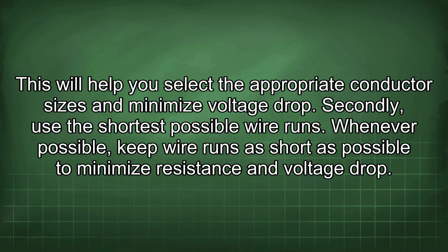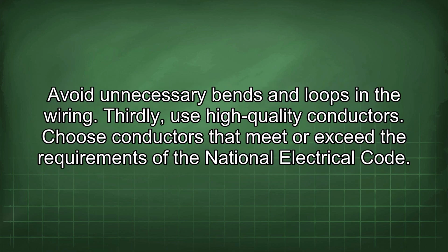Secondly, use the shortest possible wire runs. Wherever possible, keep wire runs as short as possible to minimize resistance and voltage drop. Avoid unnecessary bends and loops in the wiring.